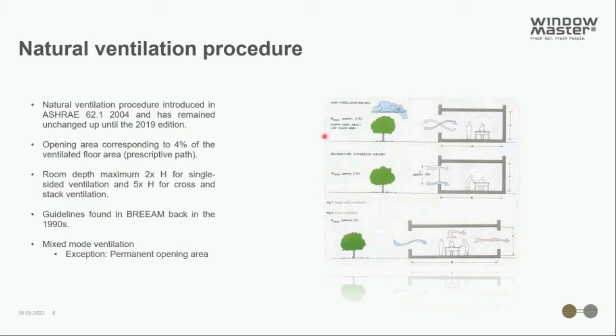Now, the natural ventilation procedure in ASHRAE is really a mixed mode ventilation procedure, as a mechanical system is required by default. However, there is an exception to the rule: if we have the opening area as a permanent opening area, we don't need a mechanical system.